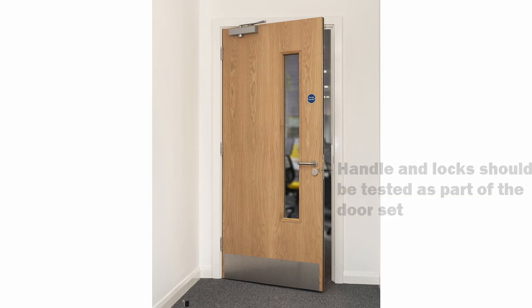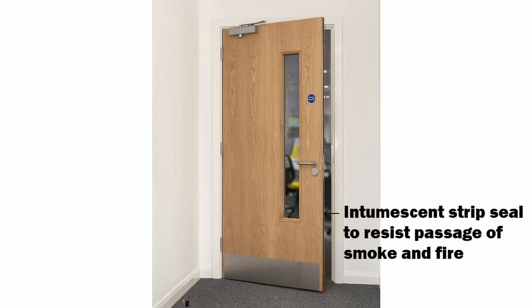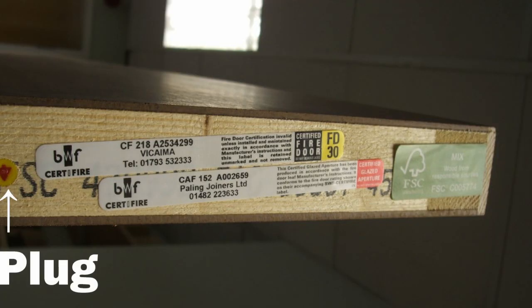Once the certification is approved, each similarly constructed fire door set will be identified by a label identifying the manufacturer, the date of manufacture, and the designated fire rating of the door type. This identification label is usually affixed to the top edge of the door. A colour-coded plug may be inserted into the door instead of or in addition to the label.